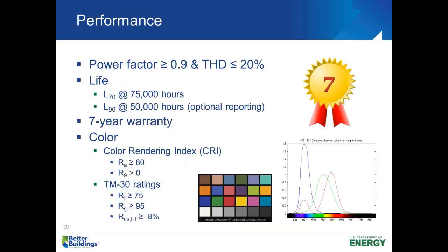With respect to performance, retrofit kits will be expected to have a power factor of greater than 0.9 and a total harmonic distortion of less than 20%. This is very typical in many of the luminaires that have been observed, as well as retrofit kits.